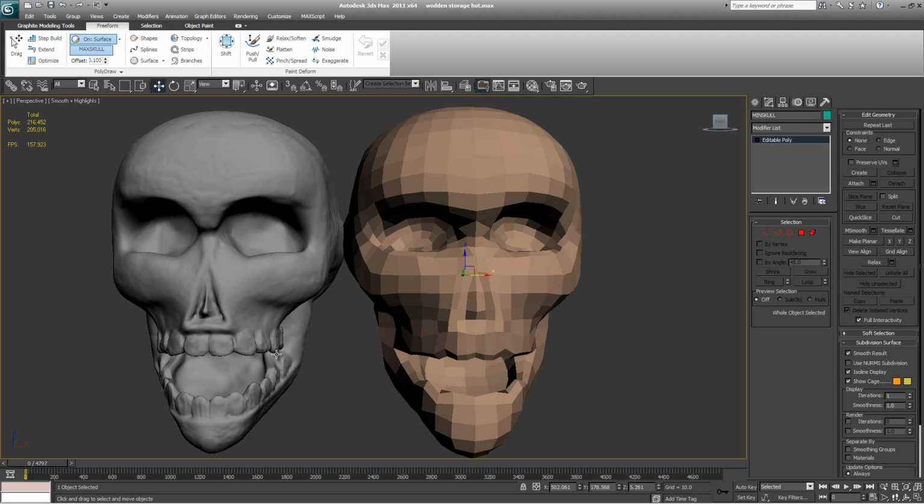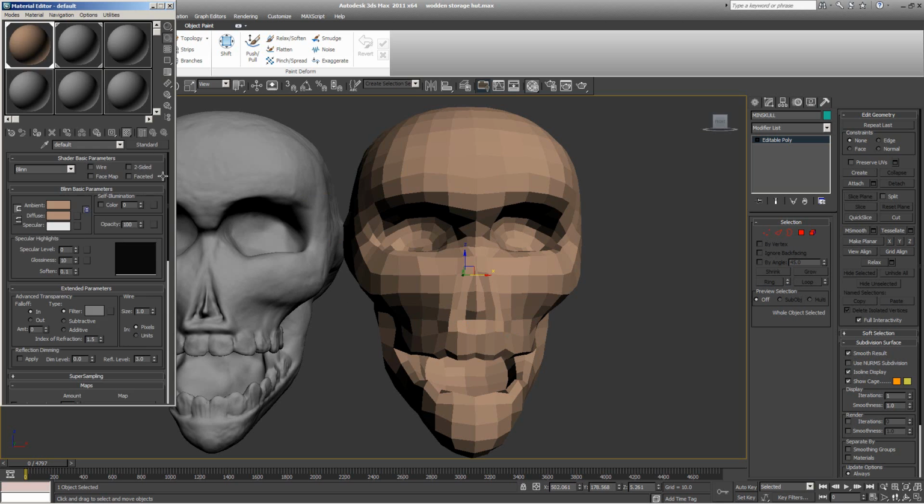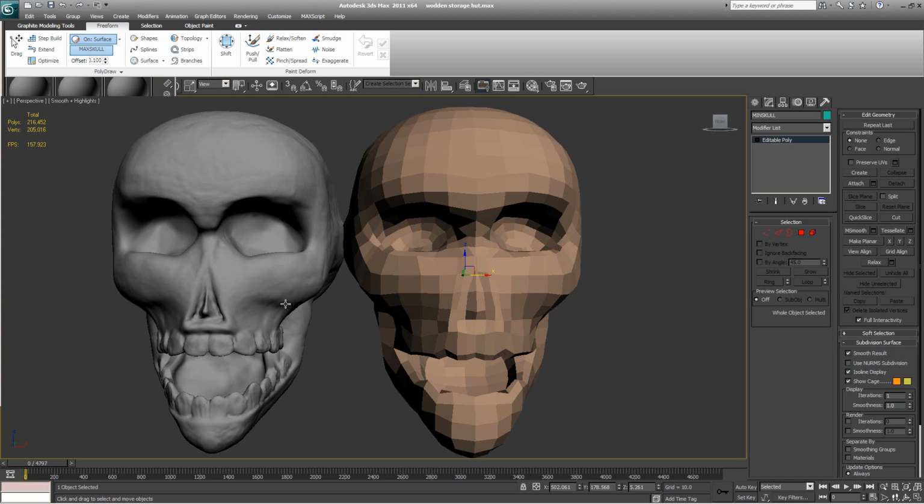And now the rest of the thing that we need to do is just to save the details of the skin, so-called texture, but not texture in the form of material or anything, but texture in the form of bumps on the skin. So we can preserve those details and scratches and store them in a texture size file, which can be JPEG or Targa, whatever we want. Stick it onto here and have those details shine under the light.